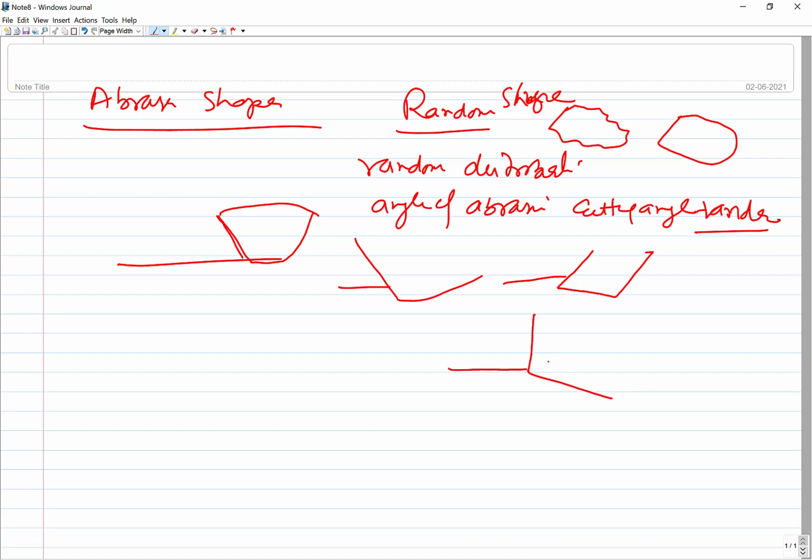So this is the edge of the abrasive which will be performing the shearing. With respect to the movement and with respect to the surface, if you see, this is about say 90 degrees. So here the angle is the rake face of the abrasive cutting edge. Here it is 90 degrees, meaning the rake angle is 0, a zero rake case.